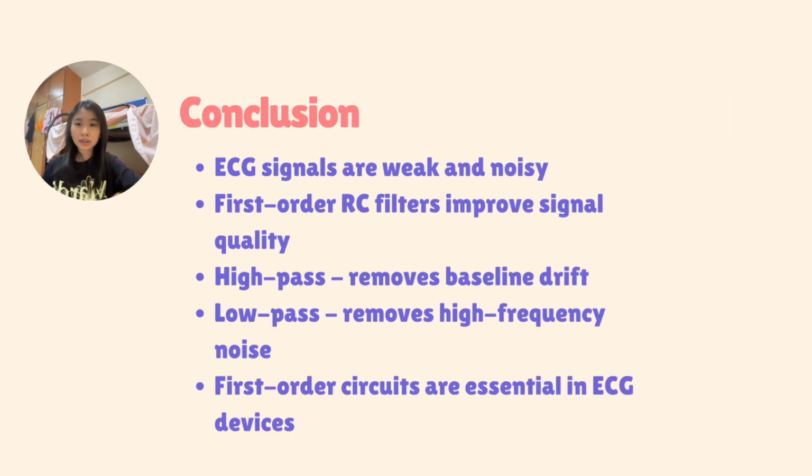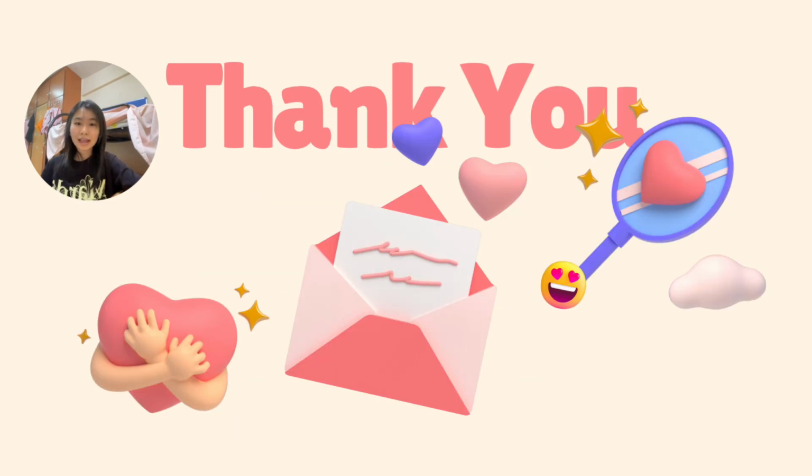In conclusion, ECG signals are weak and easily affected by noise. First-order RC filters play an important role in ECG signal conditioning by removing unwanted noise. Their simplicity and effectiveness make them essential in biomedical ECG systems.